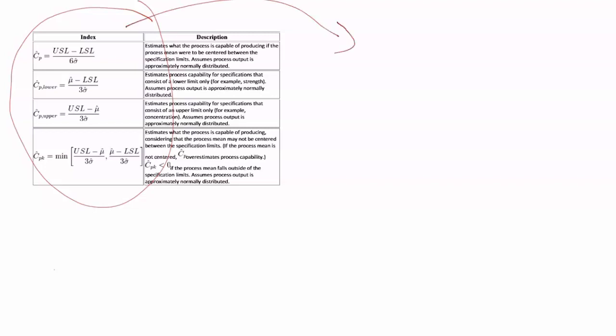And when the packages calculate the results, frequently they'll show you your CP value, your CPK value, and your sigma level of performance, and quite frequently your DPMO, or defects per million opportunities, all right next to each other side by side, because they're all related. They're all comparing the voice of the process to the voice of the customer. They're comparing process data to the spec limits.